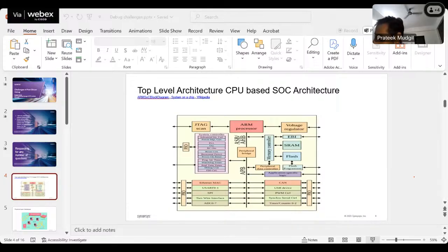We see that the maximum TCQ path and everything is met, and we find that when I'm sending some data on JTAG on this clock, it is made sure that the data comes to the memory controller on this clock, or we put some pipelines in between to meet the timings, right? So here this is the same die, and timing is already met, right?